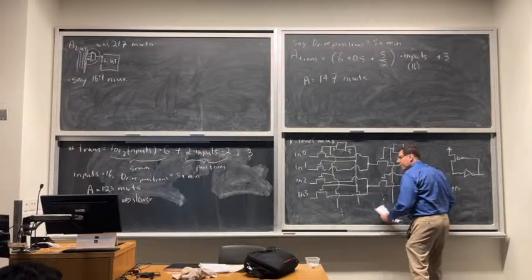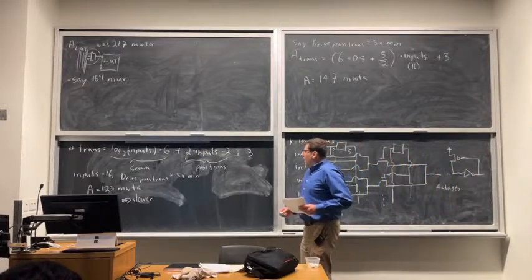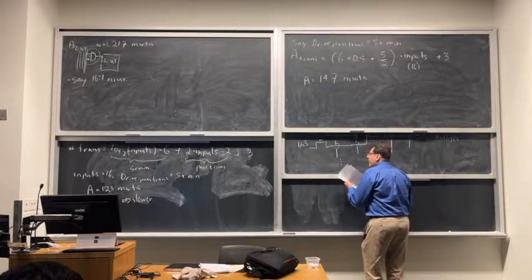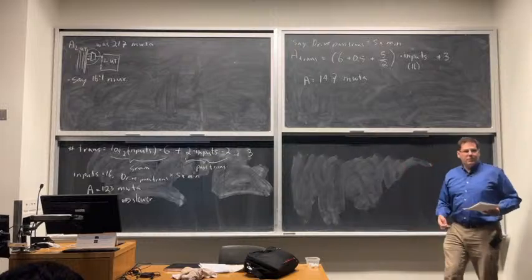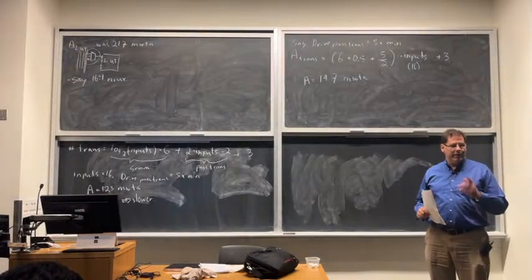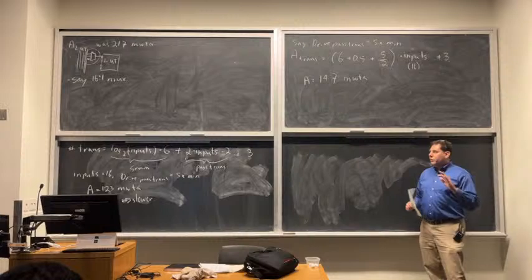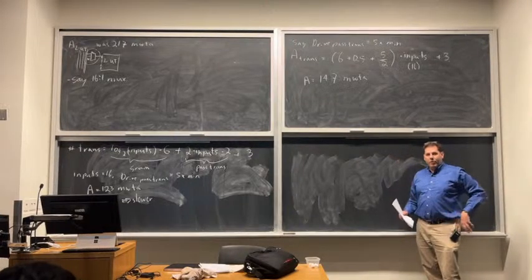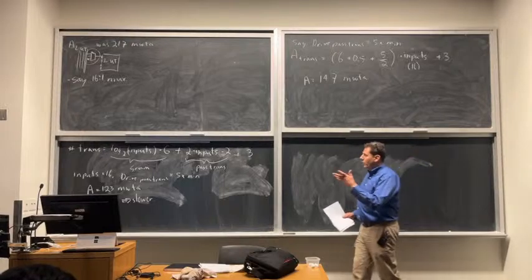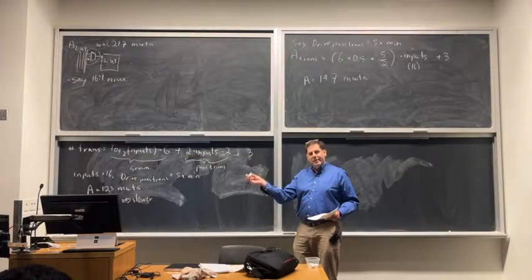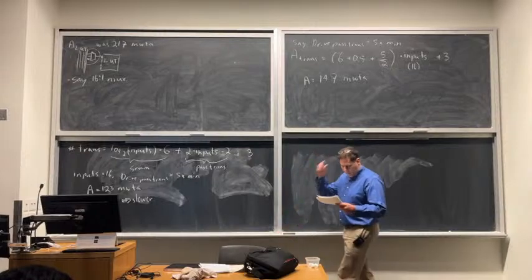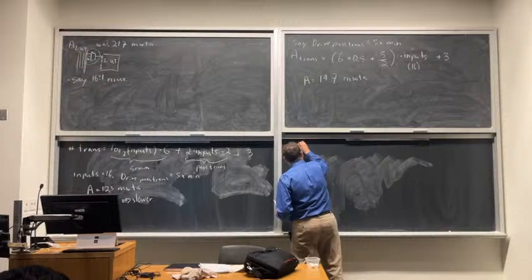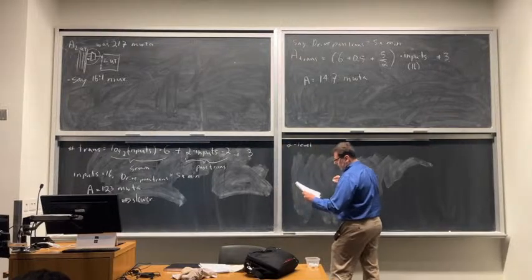Let's see, move this up here a bit. Okay, so we can also do intermediate solutions, and you already hit on this. Which is, we could do a 2-level mux. Okay, so that was for 16 inputs, that was a 4-level mux, smaller but slower than the 1-level mux. We can actually do in between points. So a 2-level mux is a good idea, and let's follow up on that proposal. So 2-level mux.